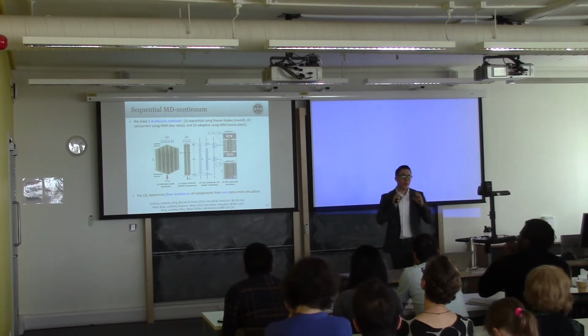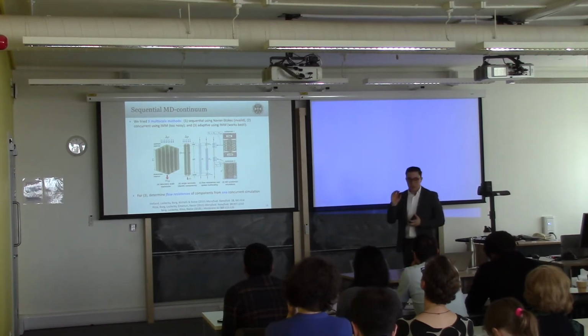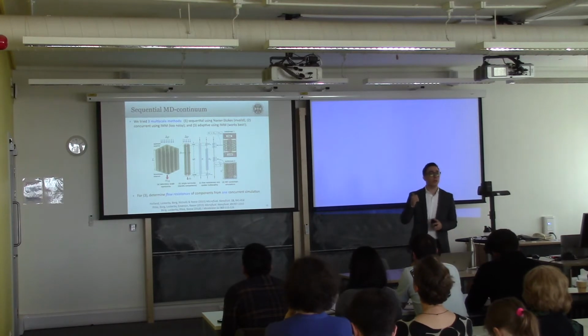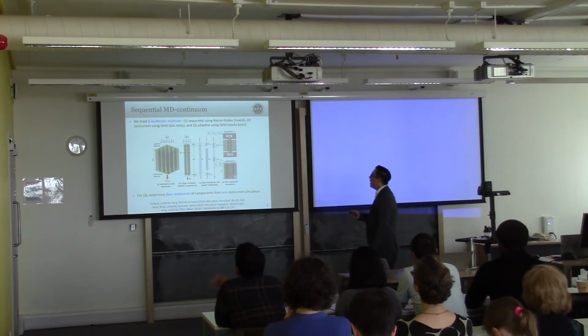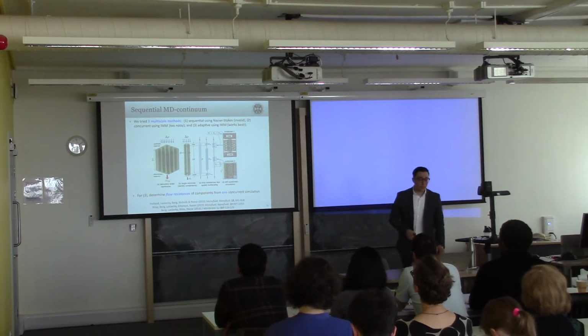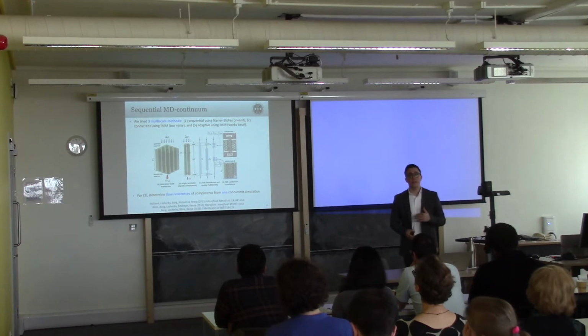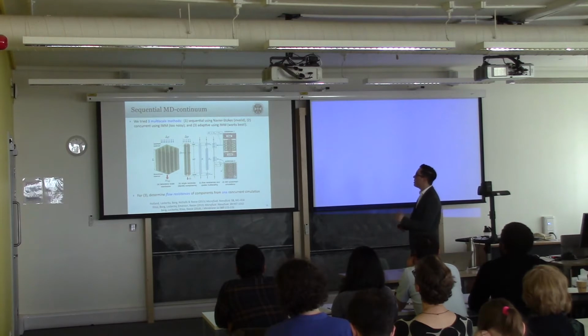We tried to run sequential pre-simulation, so we run some MD, understand what all the physics is, and try to enhance and tweak the Navier-Stokes equations as much as we can in order to compare with our benchmark case, which was a full MD simulation. And no matter how much we tweaked, we never managed to get closer than 30% accuracy with the Navier-Stokes.